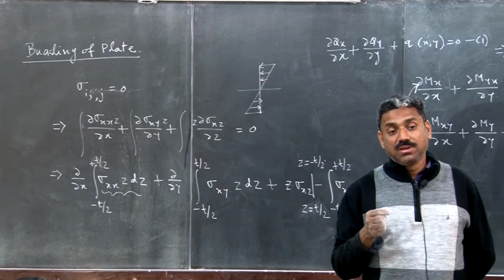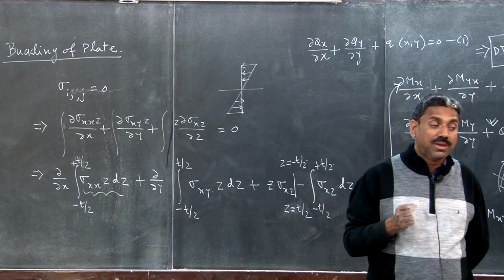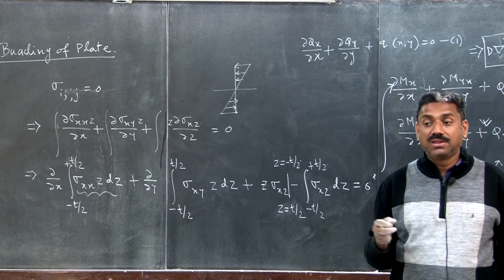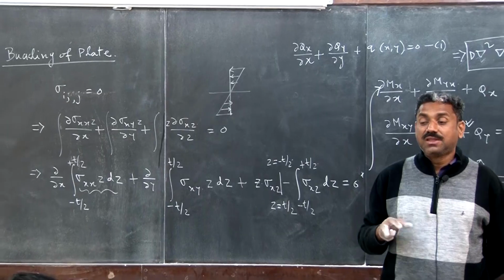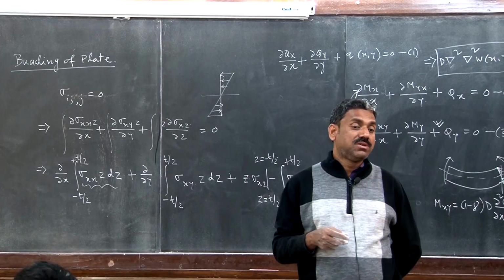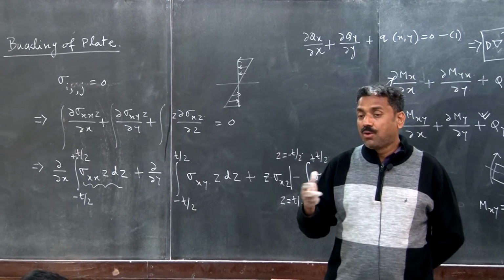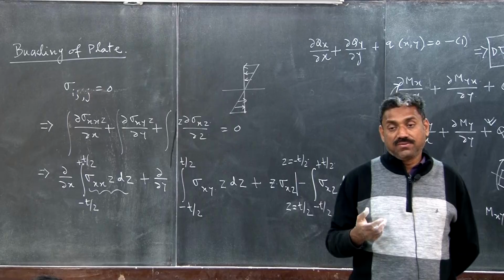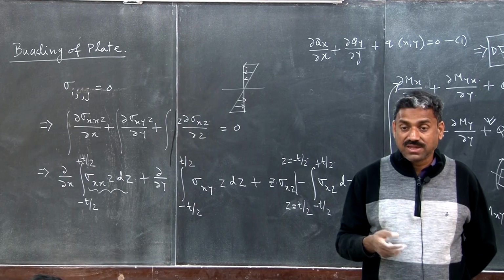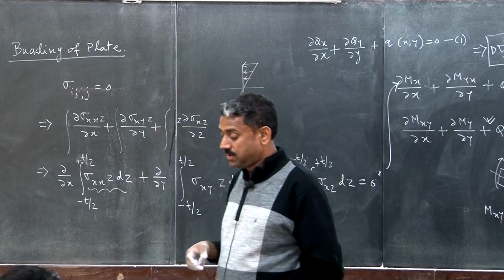Now we have to distinguish between the deformed and undeformed configuration. So you have to invoke an additional equilibrium equation where this distinction is made. That's why we have to consider the finite deformation theory. And in finite deformation theory, the equilibrium equation is written in terms of alternate stress measures: the first Piola-Kirchhoff stress measure and the second Piola-Kirchhoff stress measure. That's what we are going to discuss in the next class. Okay, for today let us stop here. Thank you.